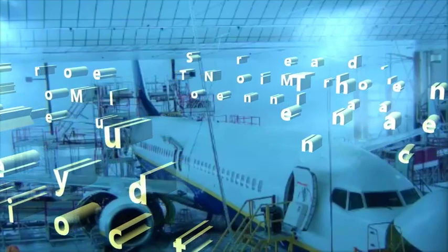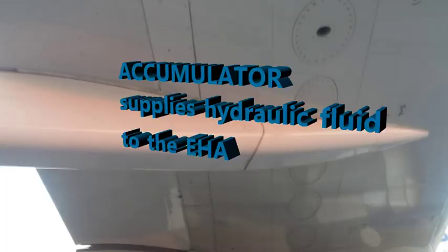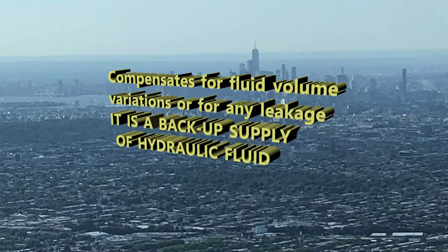Also, of course, you have reservoirs, so that you have hydraulic fluid moving and going where it needs to go to the actuators. But you also have an accumulator that's supplying fluid to the EHA. In this particular case, an accumulator is supplying the hydraulic fluid to the electrohydrostatic actuator, compensating for the fluid volume variations and any leakage. So again, it's a backup reservoir, and that's what it's there for.